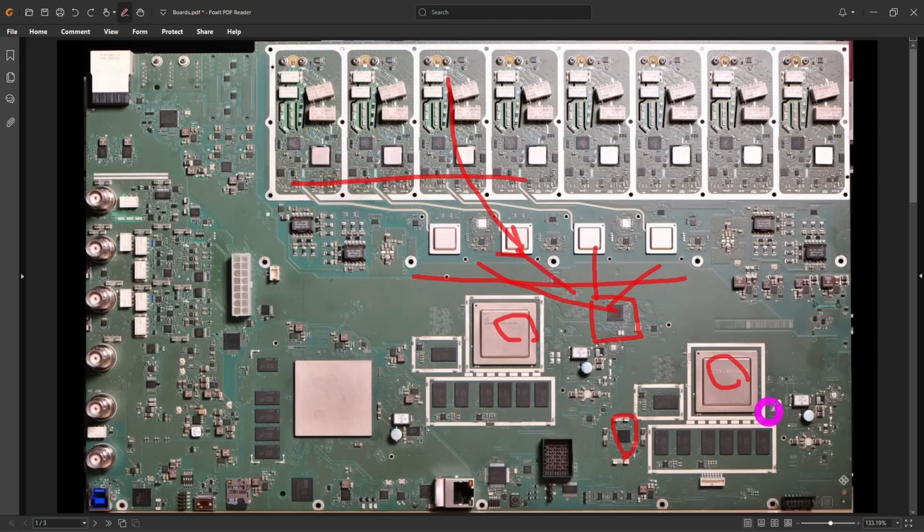A few other noteworthy things: we do have a 2-channel 1.25 gigasample per second 16-bit DACs over here, which are feeding two identical paths. You can see the differential lines on the PCB. These are the two outputs of the arbitrary function generator. They have their own relays for range switching. There are current feedback op amps and everything for conditioning the signal to the amplitude that you want and driving a 50 ohm output. They do have their own dedicated cages too, because they put out a lot of signal. You don't want that to interfere with everything else.